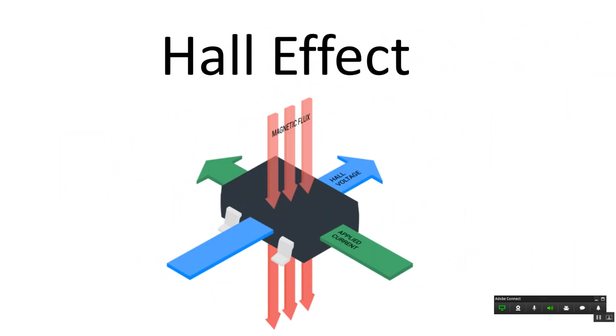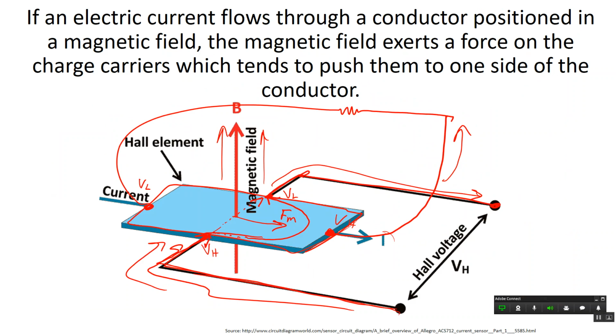Why is it useful? Like I said, you could activate a part of the circuit by bringing a magnet close to it, right? So if you, as a user, bring or turn on or somehow provide a magnetic field, you can activate that second part of the circuit. Remember, I said let's say that this end of the plate was connected to another resistor, and this resistor does whatever you think it needs to do that's important. You could activate this circuit by bringing a magnet close to it, by providing a magnetic field here. All right, so that's the Hall effect.